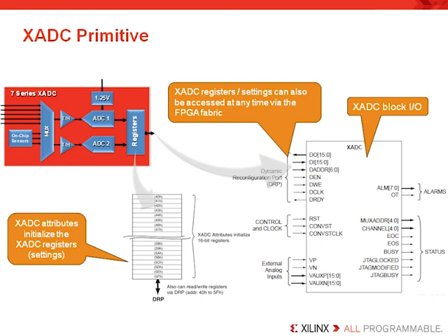The XADC operation can be user-defined at runtime by writing to the control registers via the Dynamic Reconfiguration Port. With the processor IP cores available for FPGAs, it is possible to create an autonomous processing platform which can configure and control the XADC core.